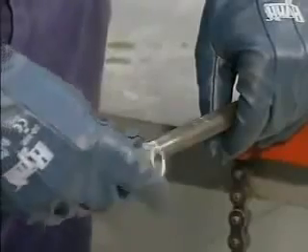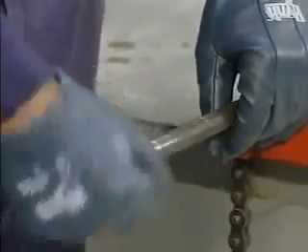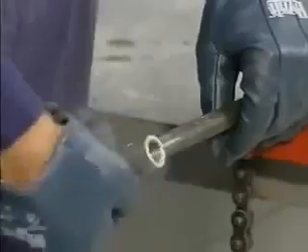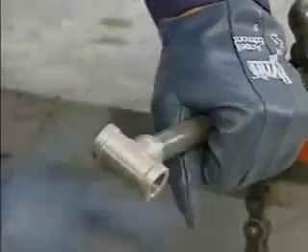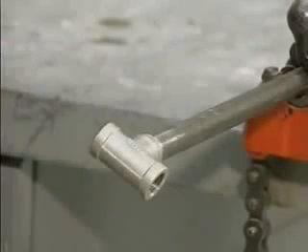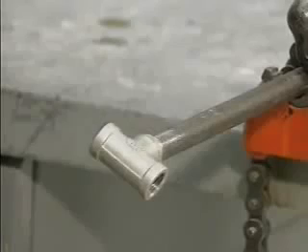Threaded joints or screwed joints are made by screwing the outside threaded end of a pipe into the inside threaded end of a pipe fitting. Threaded joints have a specified engagement depth. The engagement depth is the distance that the pipe must be turned into the fitting. The engagement depth requirement must be reached for the joint to be properly threaded.